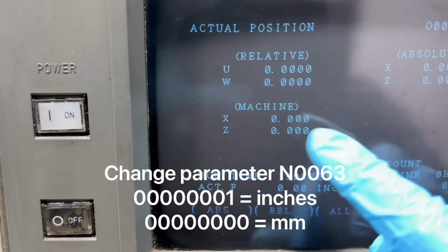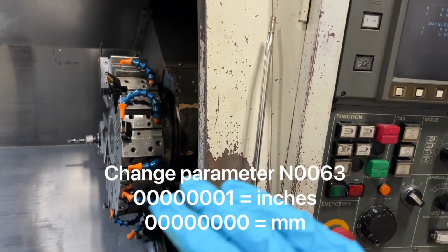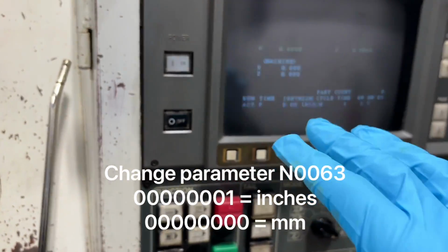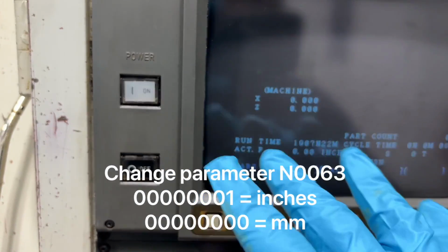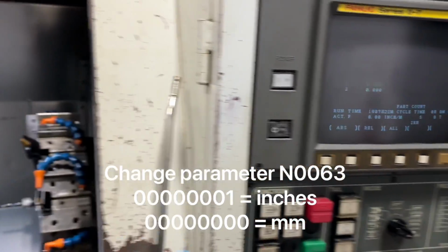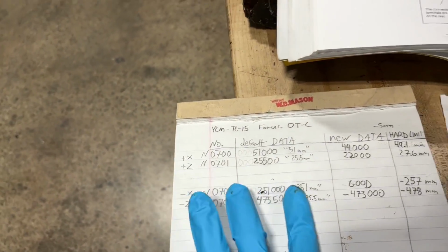So you notice how the machine is in millimeters right now? I'll show you how to set that back to inches, but when you're doing work with parameters, you want to have this in millimeters because it makes things a lot easier when you're messing around with your soft limits and finding out where your hard limits are. That's what I was doing earlier with this sheet here, but we'll talk about that after.